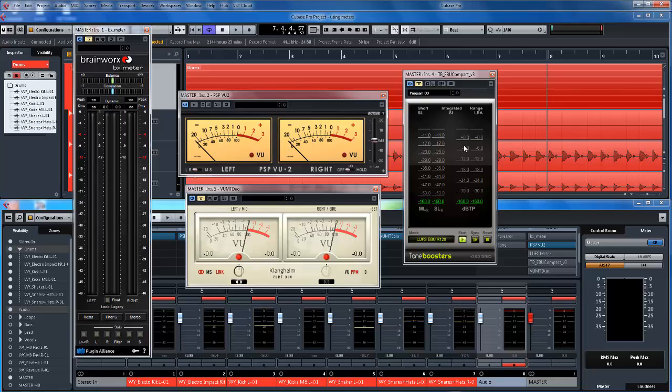The True Peak, because of its extremely fast integration times, will capture intersample peaks. I've explained this in another video and showed you how to control them. Most intersample peak problems are handled with just extra headroom. I've consistently maintained that intersample peaks are integral when you're mixing. Some people say, no, ignore them. The more headroom you have, you can stop worrying about them. But that's nonsense. True peak meters have to consider intersample peaks.